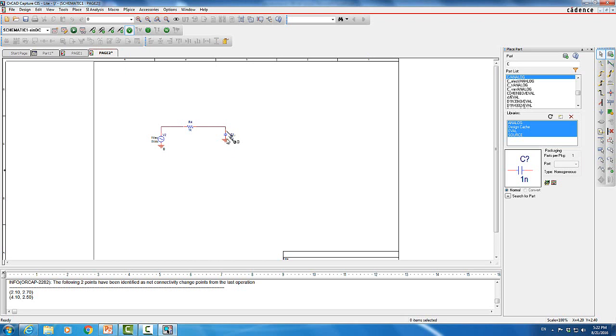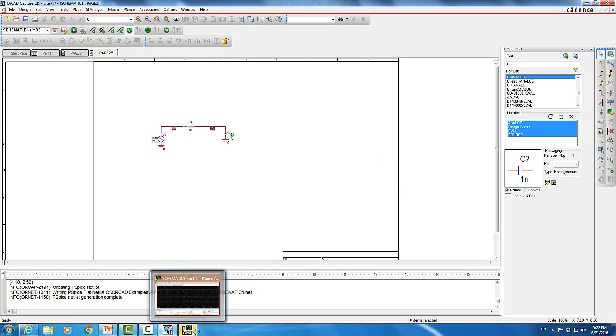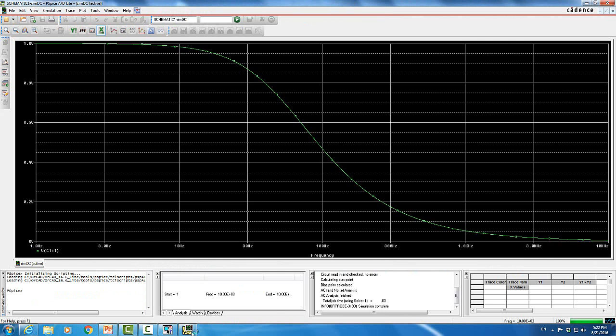Basically, we are doing the frequency response. What's the response of the output as we change the frequency, right? So we're going to run the simulation. Again, simulation is very fast, and you can see that this is the gain when I hit 0.707. I'm gonna be somewhere around here. It's more around 50 Hertz, right?